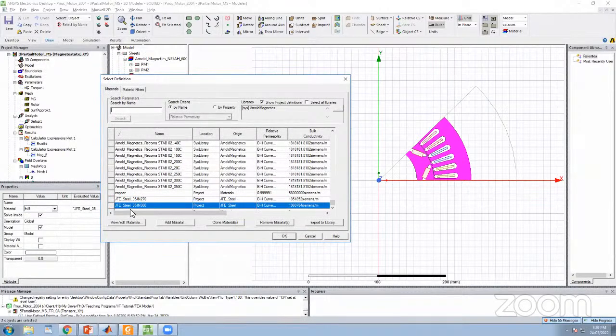The first two digits normally represent the thickness of the lamination, meaning the lamination we want to use in the motor is 0.35 millimeter thick. Then you need hundreds or even thousands of this kind of laminations to get the rotor stack and the stator stack that is 83 millimeter long. So that's why it is called laminated rotor, laminated stator.